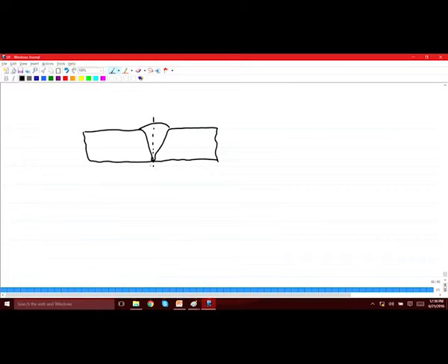Okay, so this root has a particular round kind of shape, and let us say the root diameter is d. And if you keep the probe at half skip, then this will go to the root. And you will see on the display a signal like this.